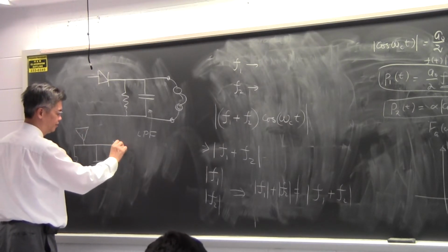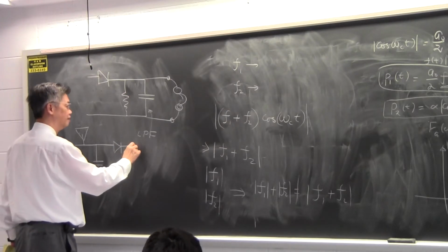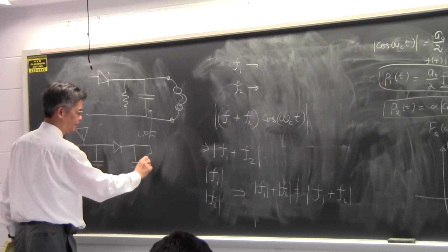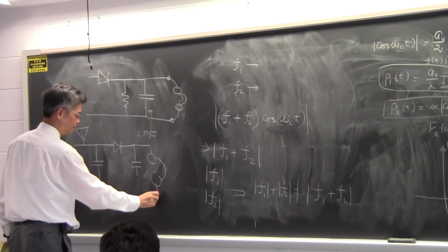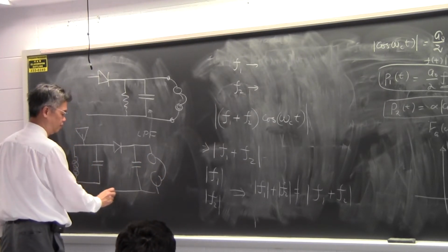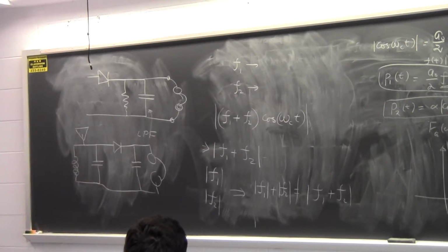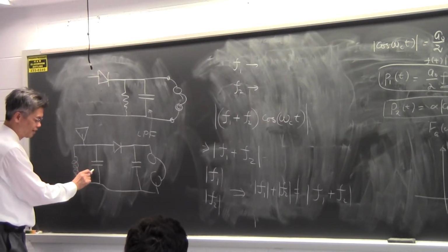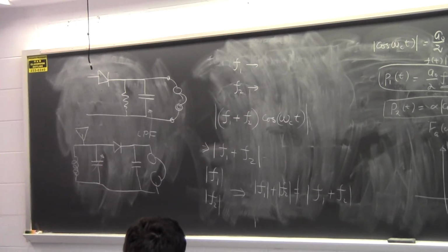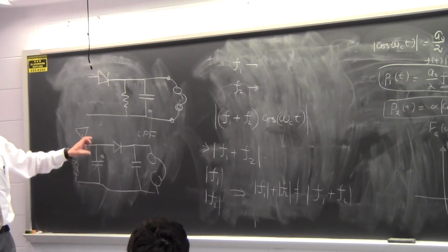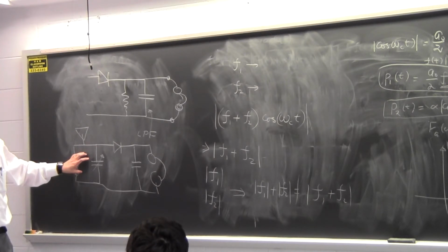Connect this to an antenna. Put this through the diode, and then put it to a capacitor here, and then connect to your earphone. Your earphone is like a resistor. Okay? You can make this very simple radio. And you can change the capacitor with a variable capacitor, so that, say, if AM580 comes in, you tune this capacitor so that this becomes resonant at AM580, or